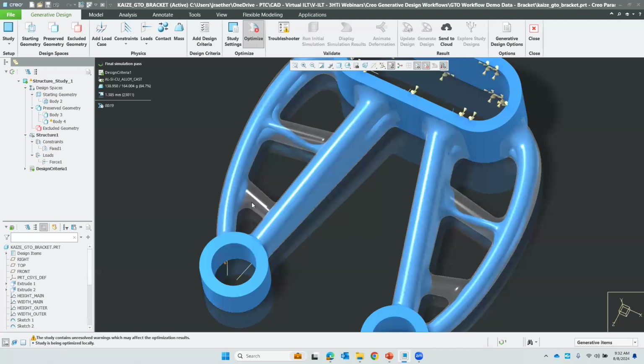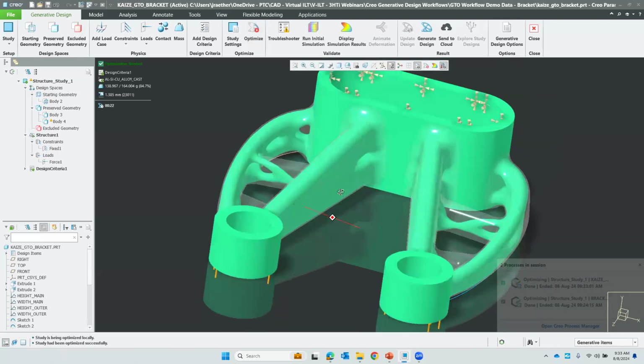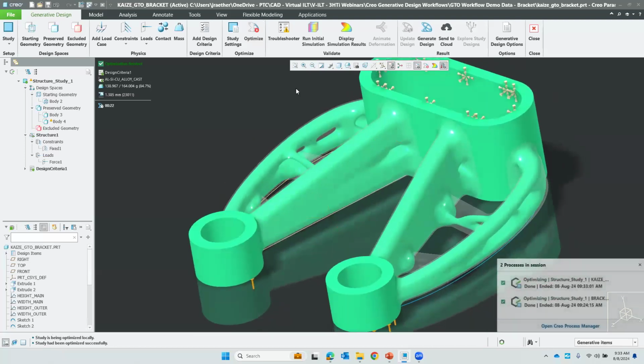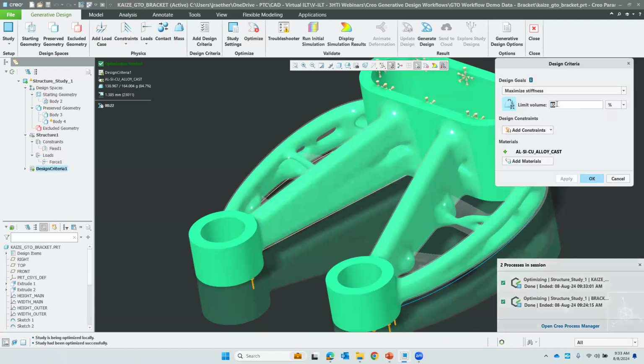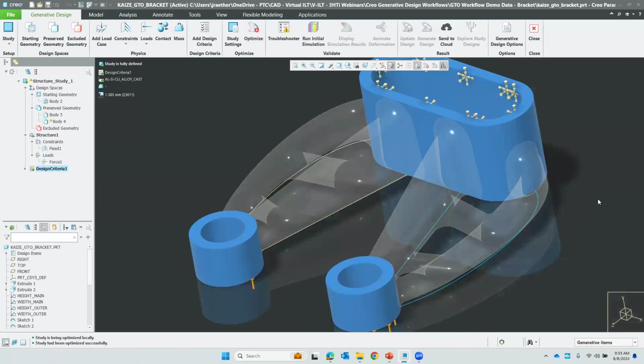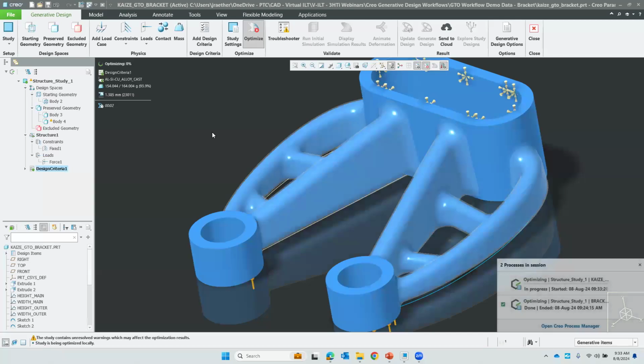So very quickly, it already started to get rid of these inner supports. And the more I back it off, right, there's the first iteration. If we go and do another quick change to it, let's maybe go to the 65. And within a very short amount of time, I'd be more than confident, not only what I saw before in CSL, I saw the stress in the main beam, but now using this, quite positive that the outer and these inner supports are not even needed.